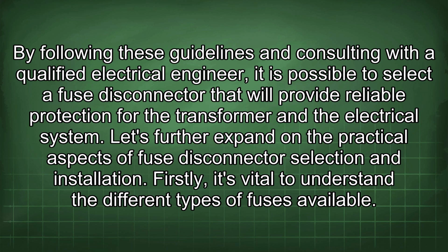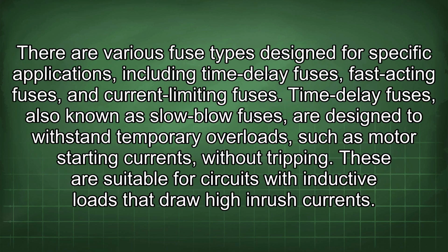Let's further expand on the practical aspects of fuse disconnector selection and installation. Firstly, it's vital to understand the different types of fuses available. There are various fuse types designed for specific applications, including time delay fuses, fast-acting fuses, and current-limiting fuses. Time delay fuses, also known as low-blow fuses, are designed to withstand temporary overloads, such as motor starting currents, without tripping. These are suitable for circuits with inductive loads that draw high inrush currents.